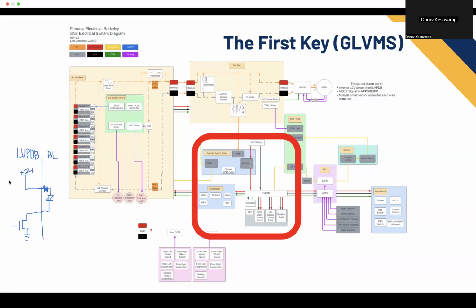A quick question on the Cat5 cables. So you said 2 pairs are for CAN, 2 pairs of the twisted wires, and then one of the other pairs is for power? Yeah, so we have one twisted pair that is plus 24 volts, and then the other twisted pair is ground. Is that kind of like power over Ethernet, or is that the same thing?